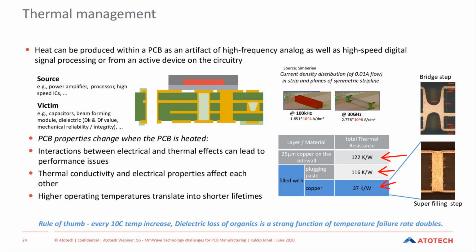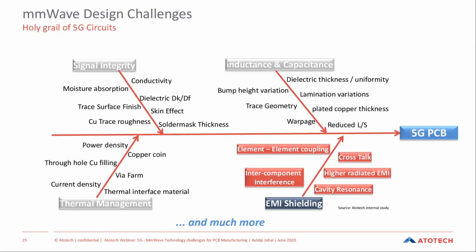Atotech has been working on this and developed a horizontal system, which is a two-step system. It requires a sort of bridge step first, followed by the filling step, which is basically filling two blind microvias at the same time, and this achieves the through-hole filling. I should also mention on the previous slide that one of the challenges is obviously aspect ratios and how far we can plate. The challenges are being pushed from 4:1, 6:1 and greater as the key areas.